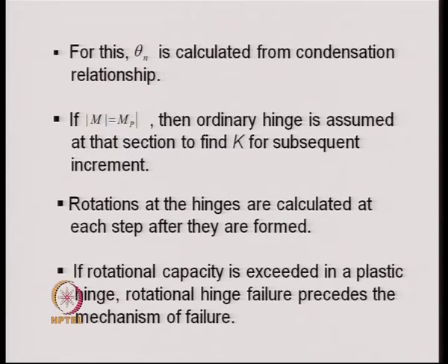Once we get that incremental rotation, we add it to the previous rotation to find the final rotation. Therefore, we can find the rotations at the plastic hinges, and we keep a record of that in order to check whether the permissible rotation capacity is exceeded in a plastic hinge or not.